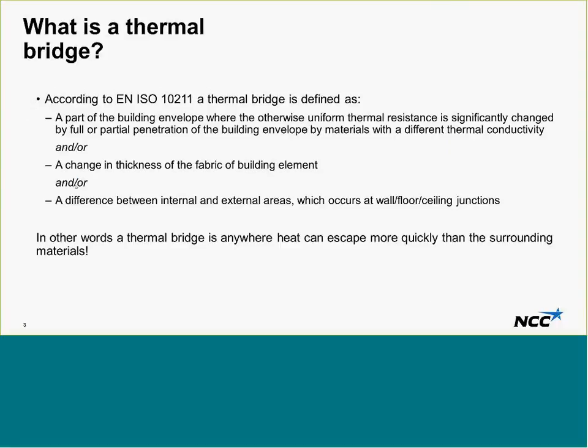So the first thing we need to know is, what is a thermal bridge? Well, according to the ISO standard 10211, a thermal bridge is defined as a part of the building envelope where the otherwise uniform thermal resistance is significantly changed by full or partial penetration of the building envelope by materials with a different thermal conductivity, and/or a change in thickness of the fabric of the building envelope, and/or a difference between internal and external areas, which occurs, for example, at wall, floor, and ceiling junctions.